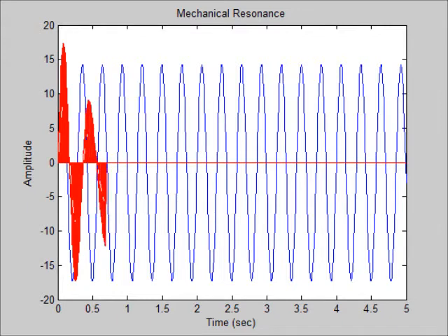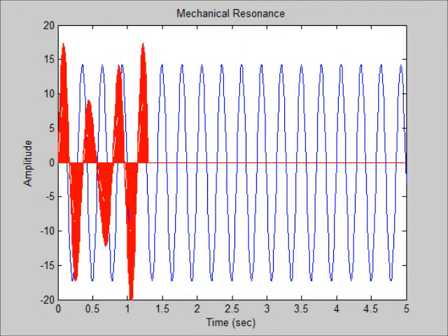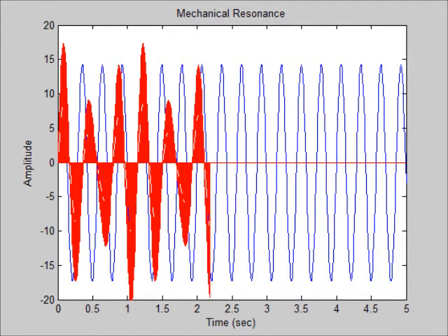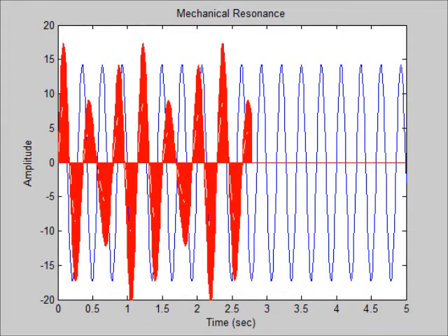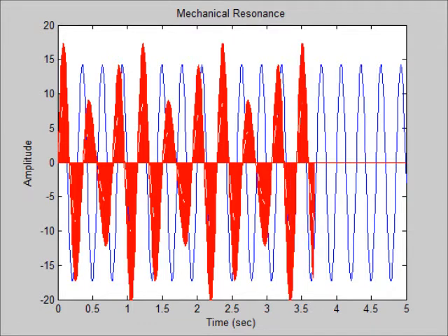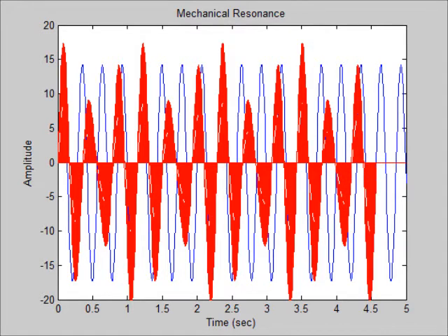The blue signal is the natural frequency of the pendulum, while the red signal is 0.75 times the natural frequency of the pendulum. So this means that every fourth cycle, the forced frequency is in phase with the natural frequency, and this causes resonance. You can also see how the amplitude increases past what the natural frequency amplitude originally was, giving a max amplitude of the system.